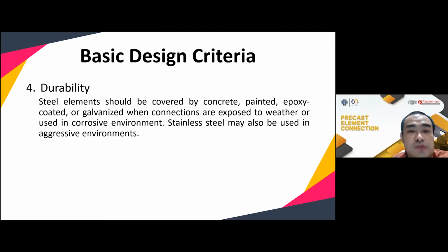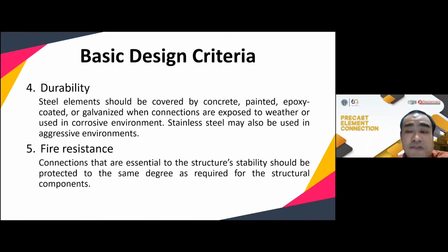Number 4 is durability. Steel elements should be covered by concrete, painted, epoxy coated or galvanized when connections are exposed to weather or used in a corrosive environment. I think Mr. Nishant also explained that the bolt is covered by grout so that it isn't exposed to the weather. Another strategy is to use stainless steel in aggressive environments. I will not talk about durability in detail because we have another session on durability in the next 2 weeks.